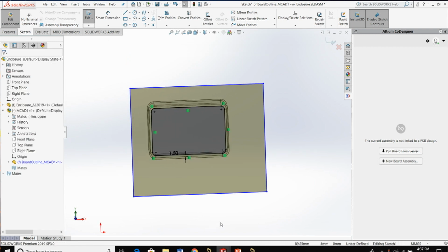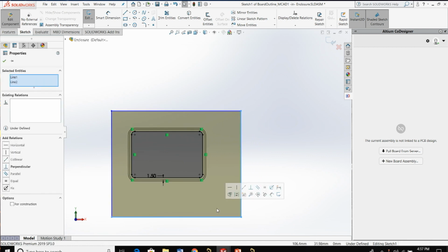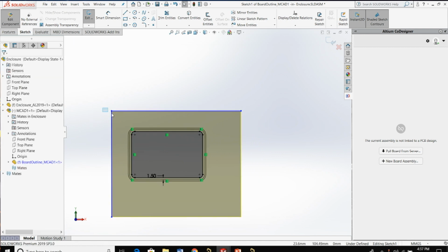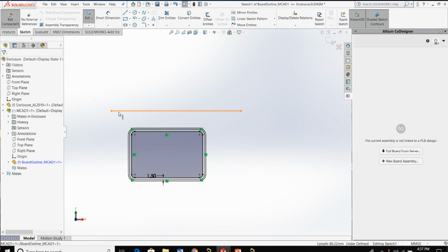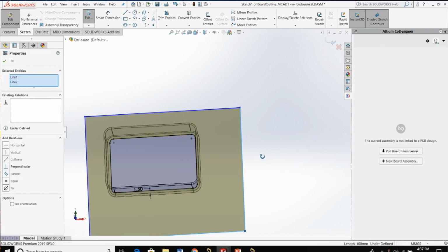And just like whenever you're creating a board shape in Altium, you can't have two enclosed pieces and try to create a board shape from all of those primitives. So we're going to remove the existing sketch. Okay, and then I should be able to rebuild this if I didn't delete something additional by accident.